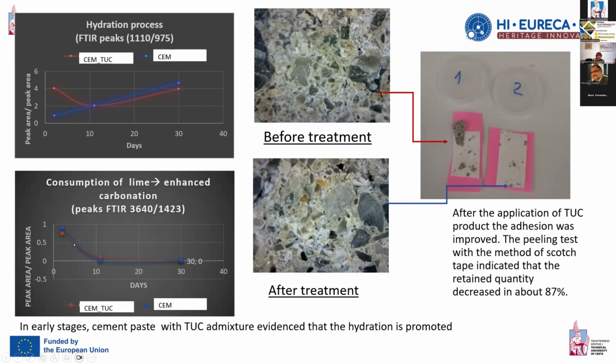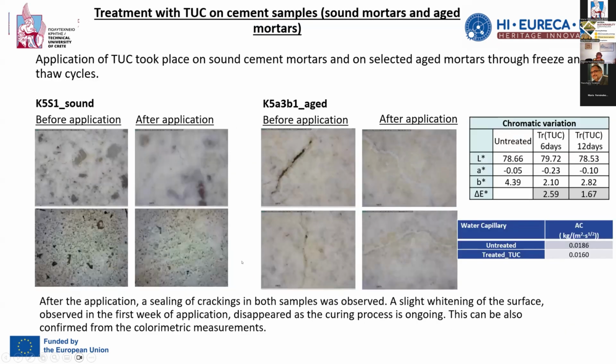And this could be explained, as we may see here, because of the enhancement of the hydration in the very early days, compared to the carbonation that continued and has more or less the same values as the product without the treatment that was applied.